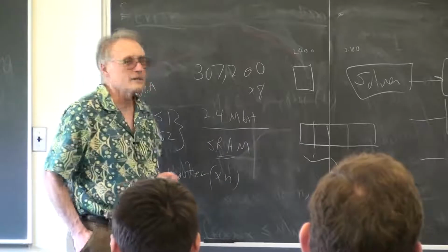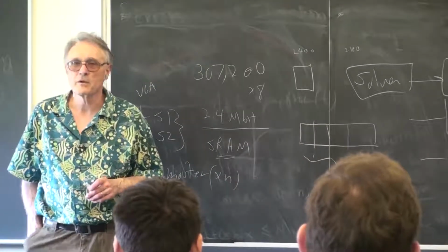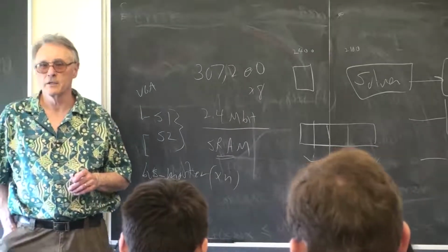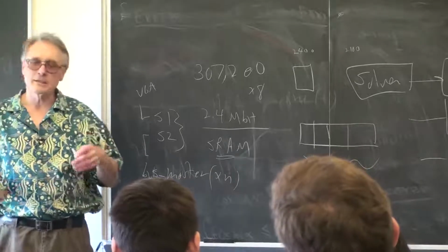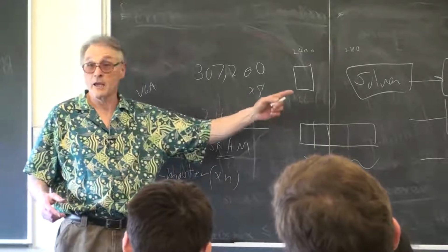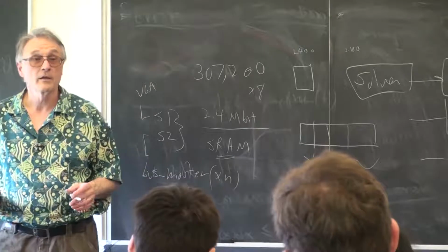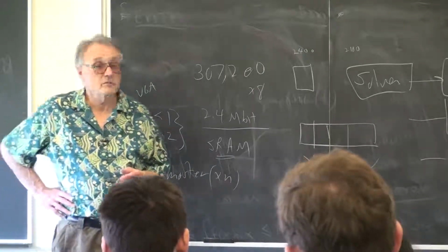And it is because of bus contention. The GPU is 3 times faster, but I can't write pixels fast enough. So after I get this documented up as working, now I'm going to try and use the internal M10K blocks to dual port the display memory.